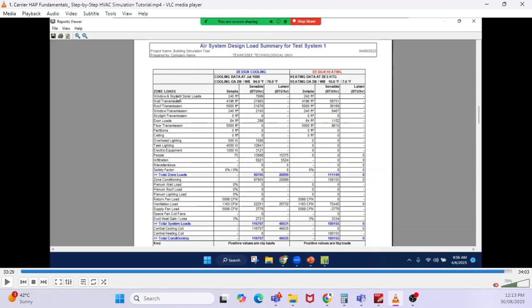Sometimes, whenever you do the selection of the machine, that heat load will be considered by your equipment manufacturer. Say, for example, you tell your equipment manufacturer, I want a 100 kilowatt machine. He will not give you 100 kilowatt; he will give you 110 kilowatt. So what is the 10 kilowatt? That is the motor load. That safety factor is the tolerance they will give you.